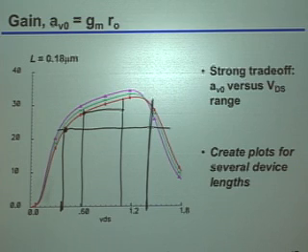That's a very good question. That is indeed exactly why we spent some time talking about what the physical effects really are, right? Because what you should expect to see is, the exact numbers are usually difficult to get right. What you should expect to see is that if you know roughly where the junction breakdown should be, that's around where things should start rolling back off. Similarly, as you change the V star, or equivalently change the quote-unquote VDsat, you should be able to see that where it starts to flatten out also moves around with that biasing.